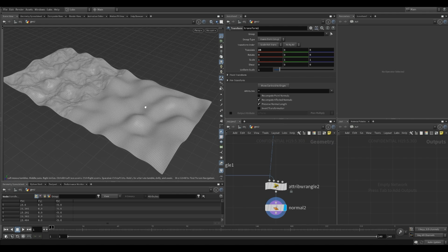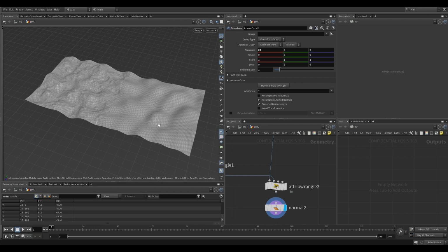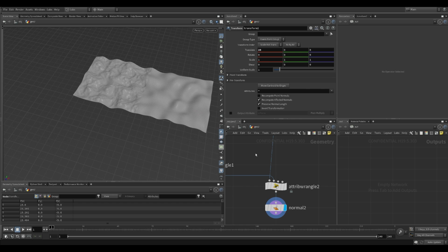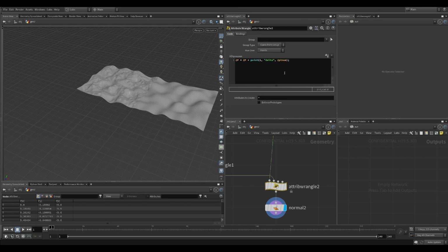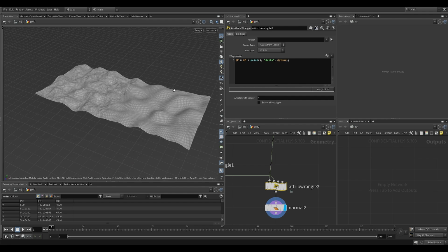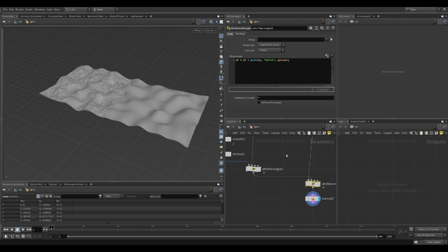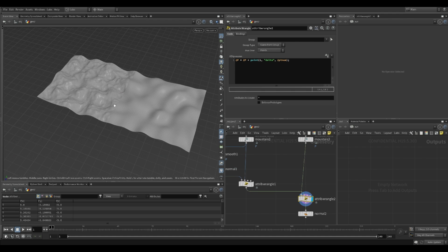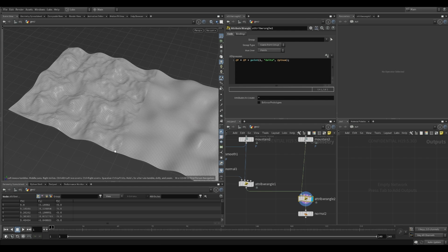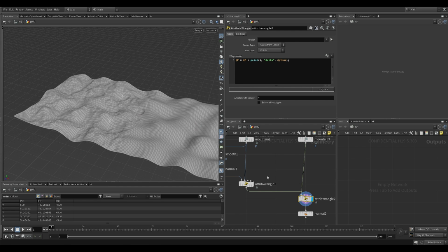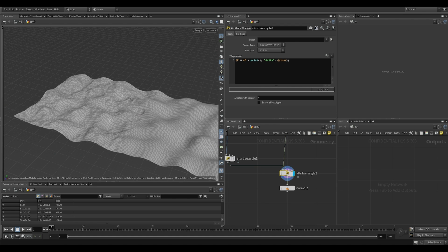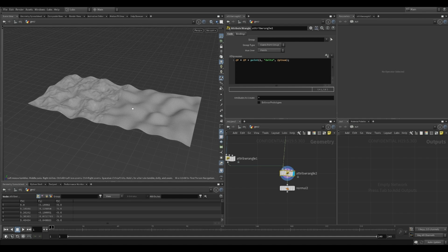and we transfer. As you can see that the right one, it doesn't get any result, because the mapping we established was basically banking on the fact that the ptnum on this side and ptnum on this side is the same, but since this side has twice as many point numbers, it only was able to establish the mapping up to the point where the ptnum can find its equivalence on the target side. After that, there's nothing being done. So this is not what we want.